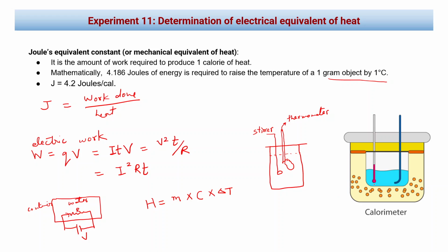So in this calorimeter, which consists of the container and stirrer setup, the heat that is supplied to the water will be the mass of water times the specific heat capacity of water, plus the mass of the calorimeter, because it will also absorb some heat, times the specific heat capacity of the calorimeter.